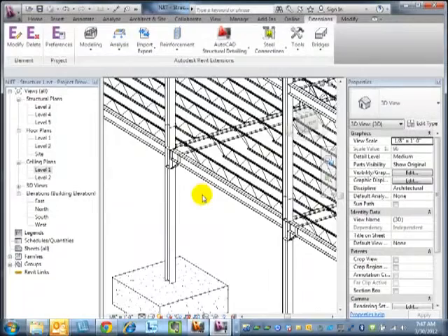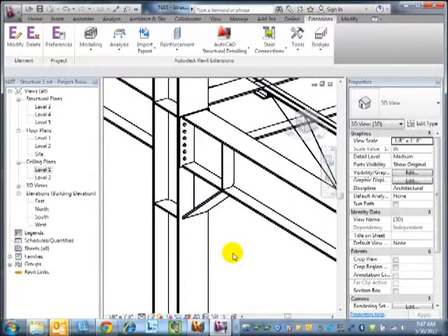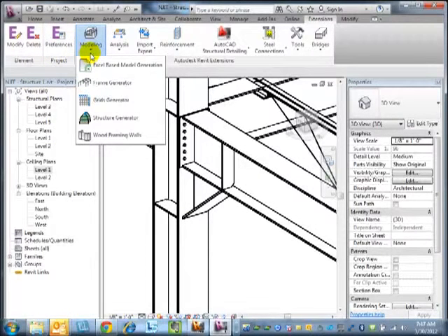Okay, so modeling extensions. Actually, what are modeling analysis? Oh sure, let's take a look at some of those. These are things that are all meant to extend it a little bit. Lots of groovy things. Wood frame walls. If you're doing a little wood frame structure, it'll go through and put the studs, the headers, the plates into the wall. It'll basically add a lot of structural framing elements to a wall for you based on the geometry of the wall. That at least won't do it for ceilings and floors and things like that, but it will go through and do walls and actually frame around the openings for you.